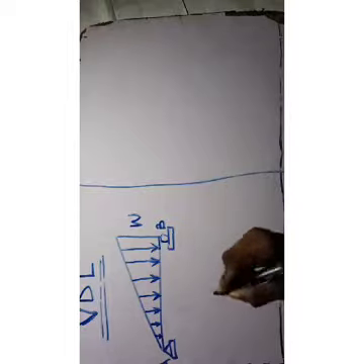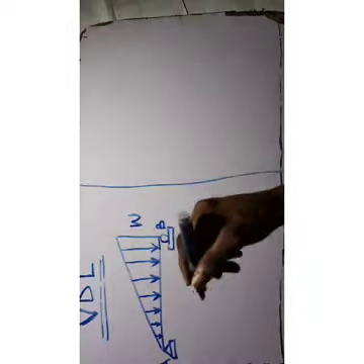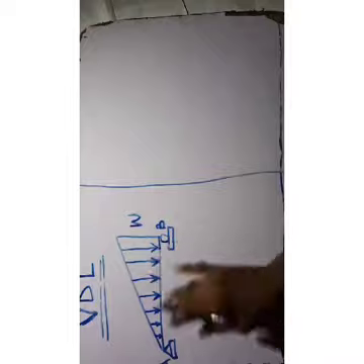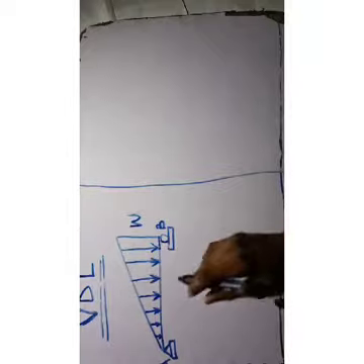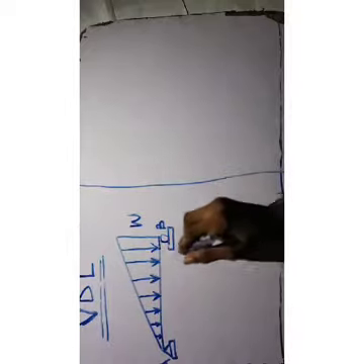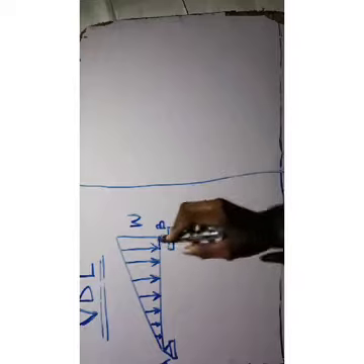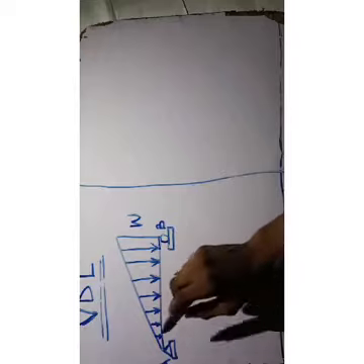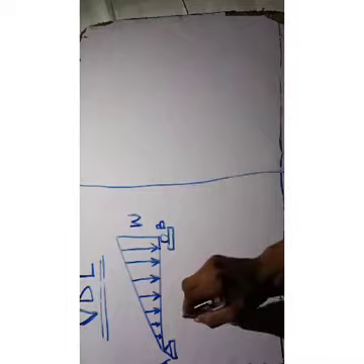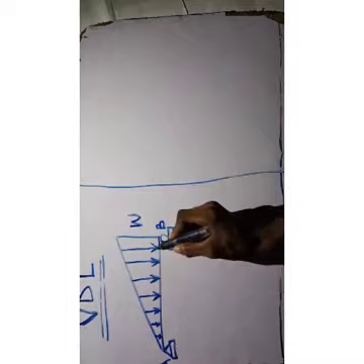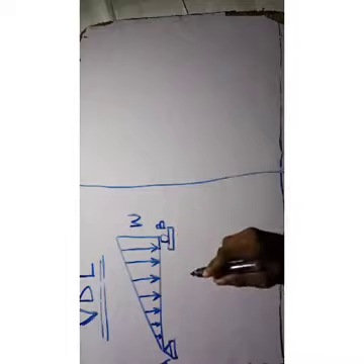But in this varying distributed load, it's not like that, but the same principle applies. First thing is that when you turn a varying distributed load to a point load, it would always act at 2/3 of the length from the smaller part and 1/3 from the bigger part. I come again, it's very important.